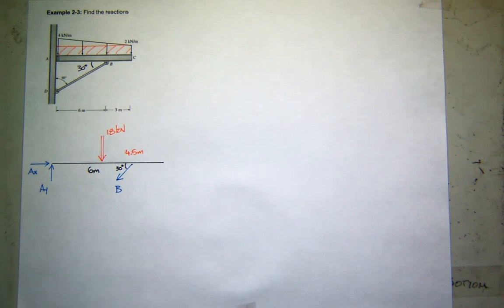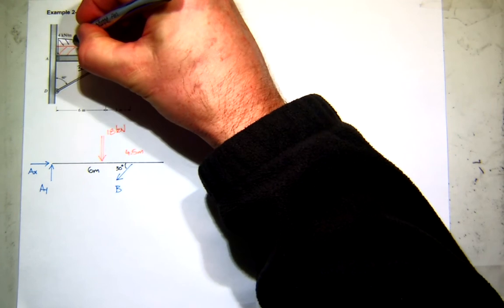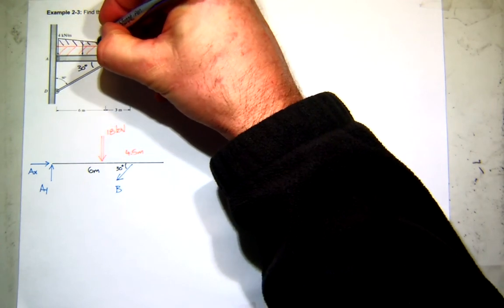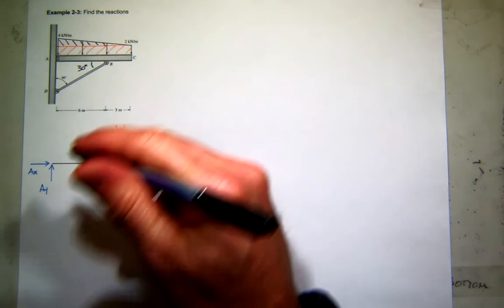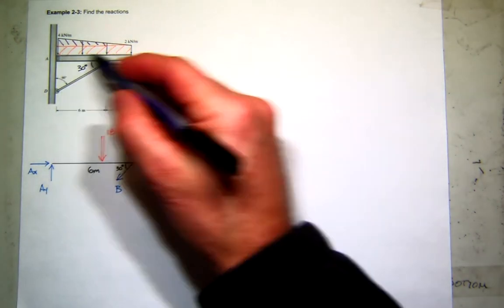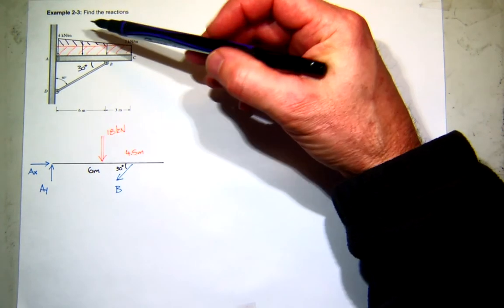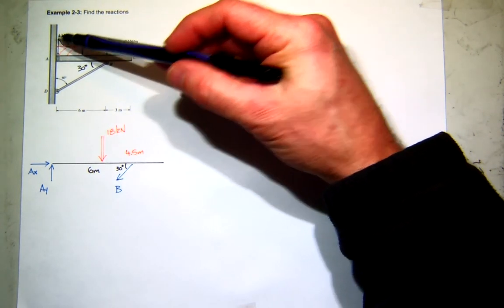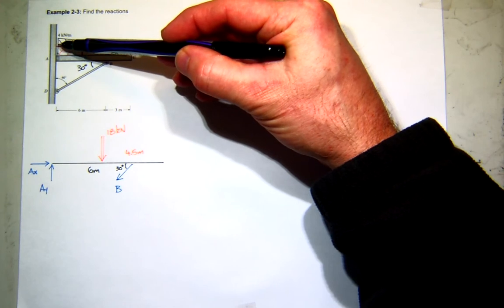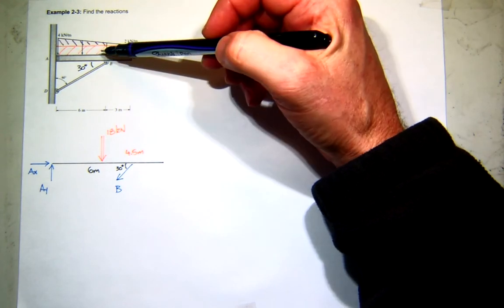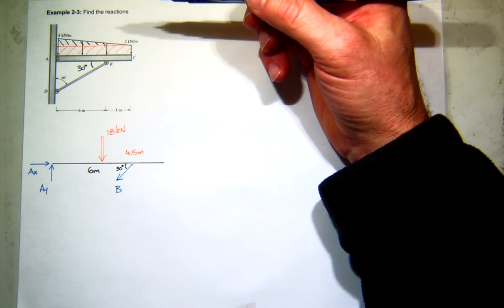And now, just to make it easier to see, maybe with color, I'll say this triangular piece is purple. What's the area of a triangle? 1/2 base times height. So 1/2 base, 9. So what's the height here? The height of the triangle? Well, the total height is 4, but the rectangle height is 2, so the height of the triangle is just 2. So 1/2 base, 9, times height 2 is a force of 9.